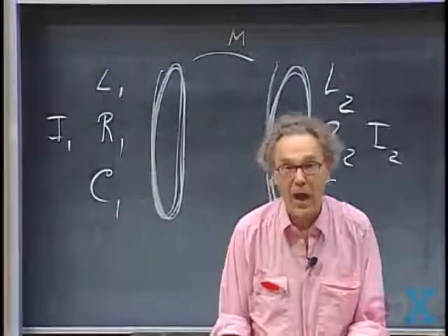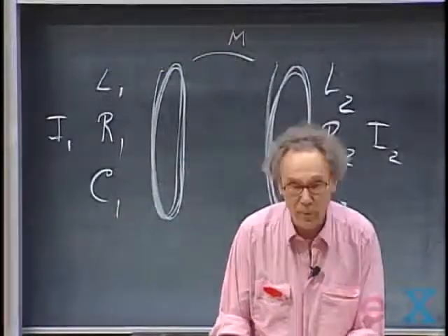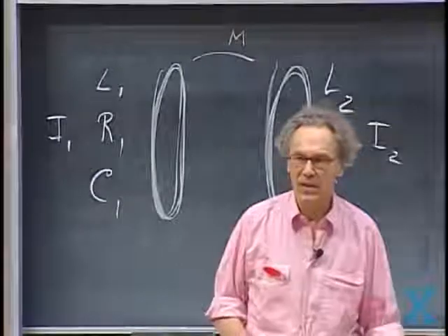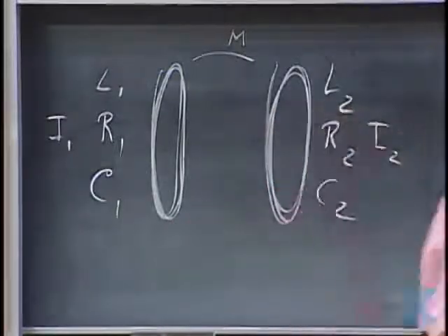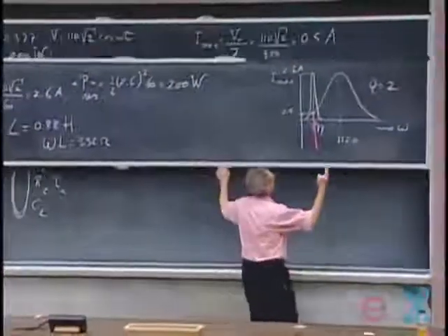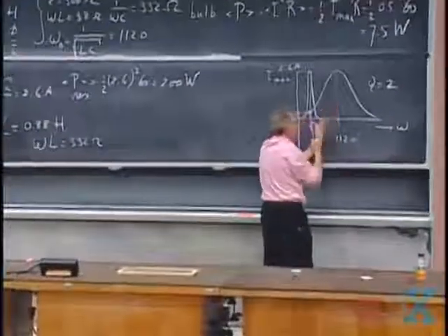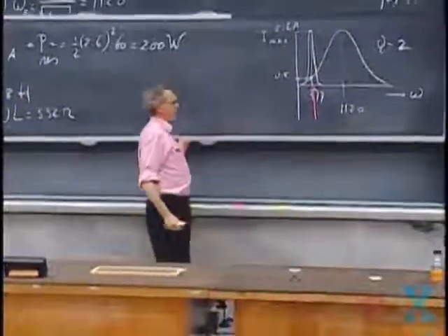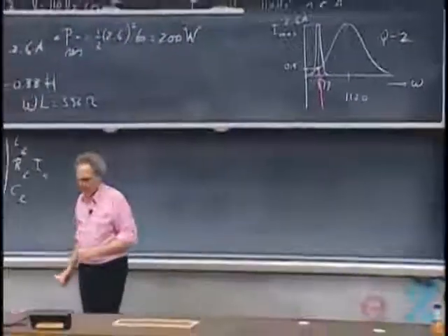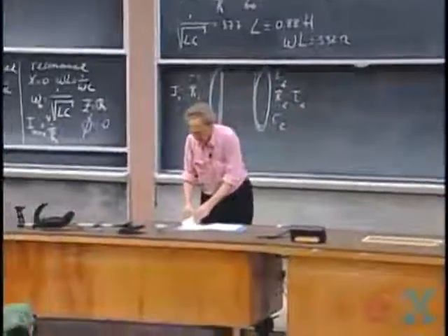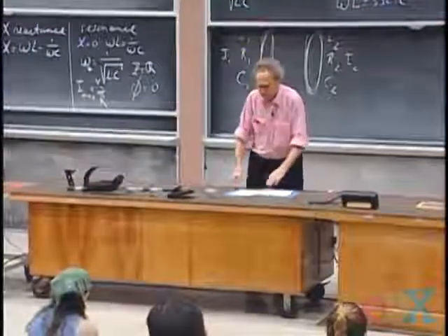These systems have very high Q. Very high Q means they're extremely sensitive. If you have very high Q, that curve is extremely narrow, and so with the slightest change in M, you go off resonance and you get your alarm. And so they come in various forms and in various applications.